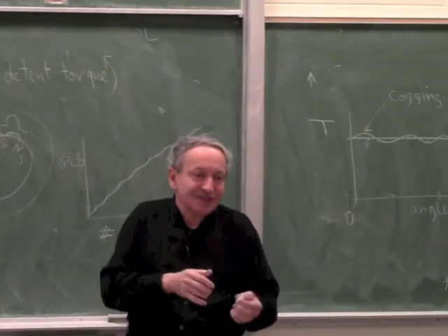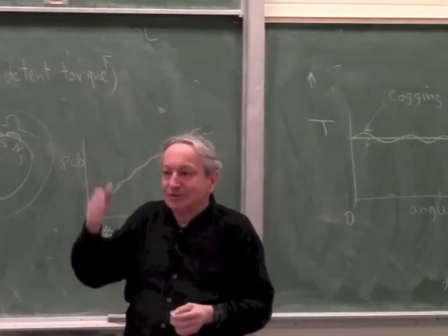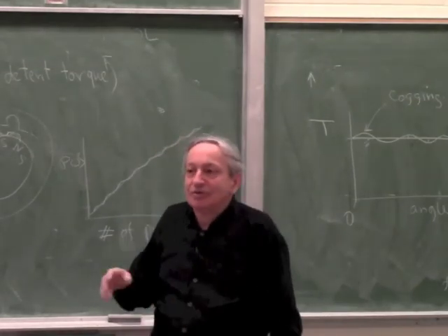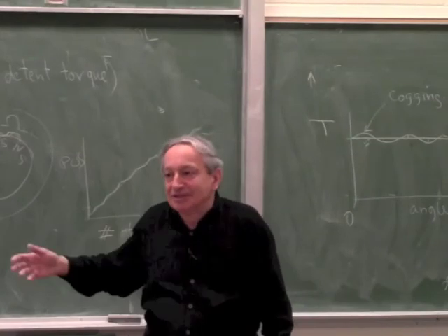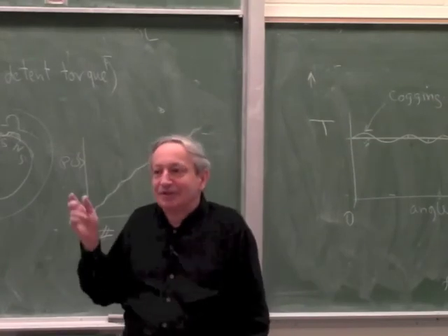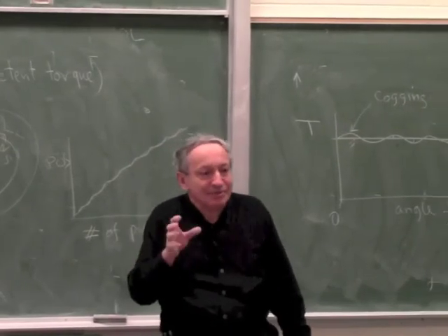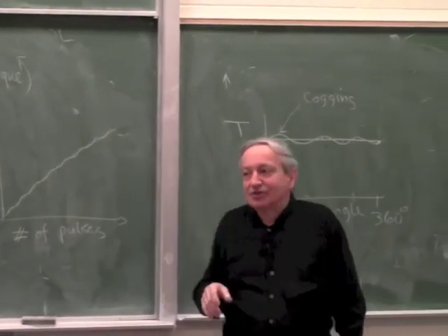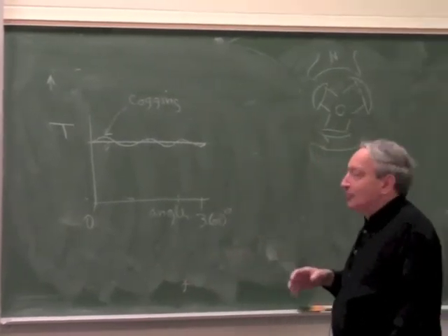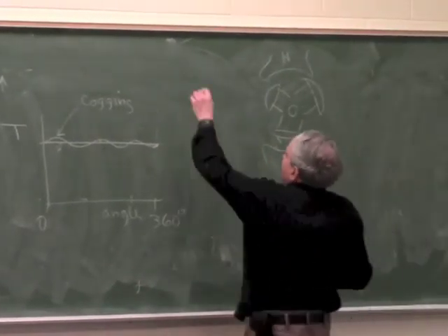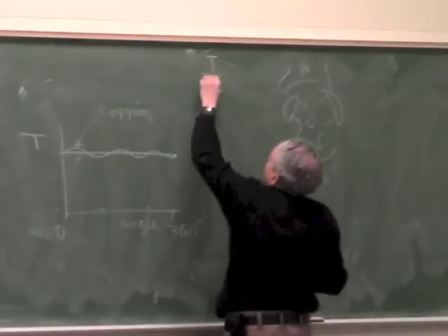Angular acceleration is torque over inertia. In a motor which has to drive a washing machine, it doesn't matter if it speeds up in a second or a millisecond. But in a servo motor, that's the key thing. That determines the bandwidth of the servo. So in a spec of a servo motor, there is a torque to inertia ratio.